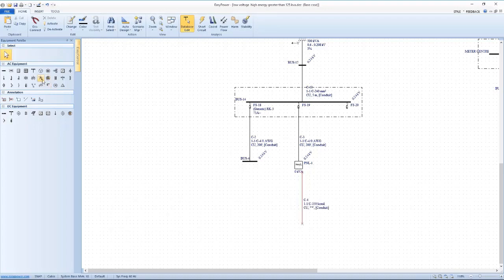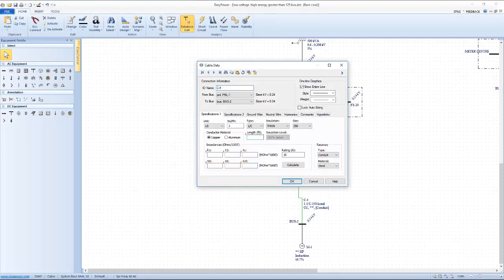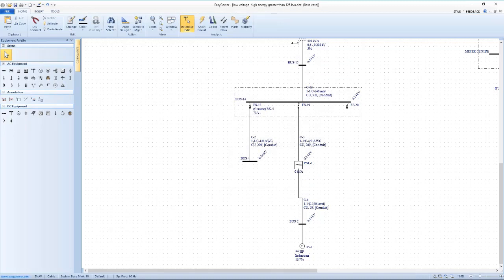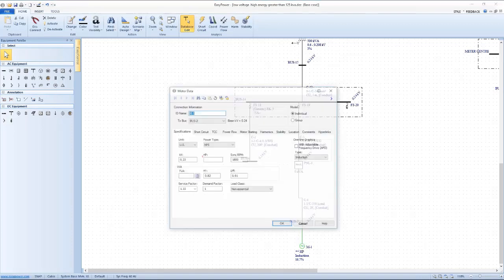So let's say we've got a motor hanging out here that's 240 volts. Let's hook this back up. Put my motor down there. So now if this motor is run out of this panel, let's just make some numbers up here. The only way I can get an arc flash label on that load is to outboard it from a panel or to represent it as a discrete load from the discrete panel. So let's say we have a 20 horsepower motor,